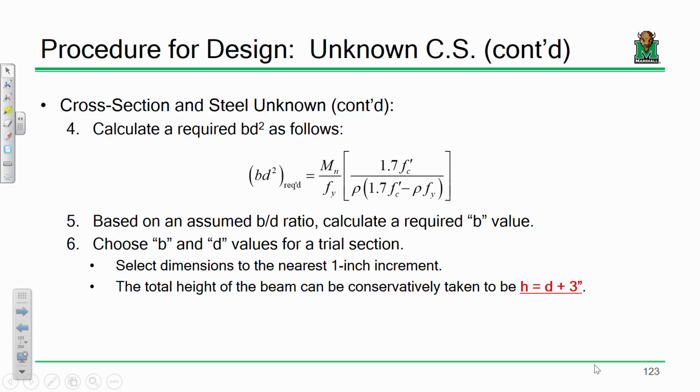This is the bottom of the beam, so let's say I've got my steel here. Well, that steel doesn't just magically float in space in there. First off, there's going to be some chairs that hold this rebar in place as you place the concrete, but we're also going to have some bars that wrap around the steel like this.